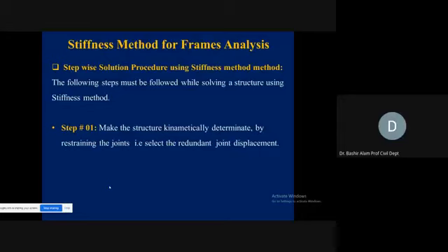Now remember, in step number 2, while we are generating the ADL matrix, from there we will also have to make our AML values. From there we are going to grab our AML values. And from the diagrams from where we are making our stiffness coefficient matrix, this S matrix, from there we will also be making our AMD matrix.